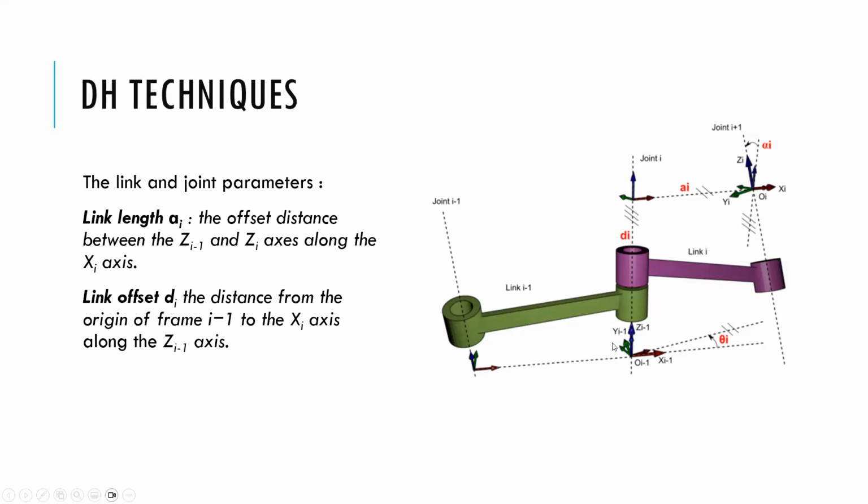Another method, and this is one of the original methods, is Denavit-Hartenberg. It's two guys' names they merged together and came up with this. I just call it DH. This is like the 1960s, around 65, right when the Puma came out. They wanted to go from one location to another location, and you can get any pose to another pose within 4 transformations. Even if this is a drone, if I want to go from one location to another, I could get there in 4 or fewer steps, if you want to talk about rotation and translation.